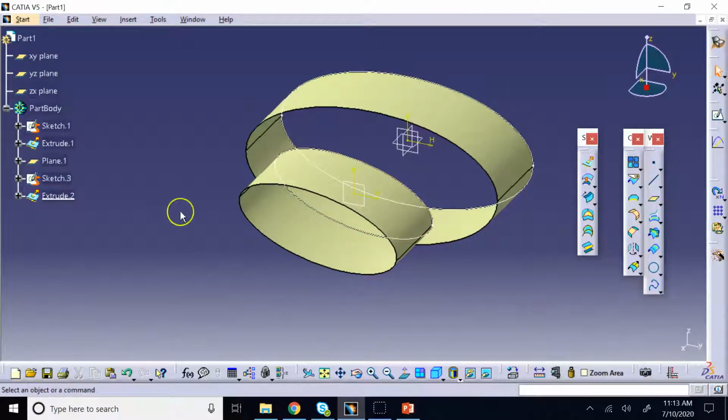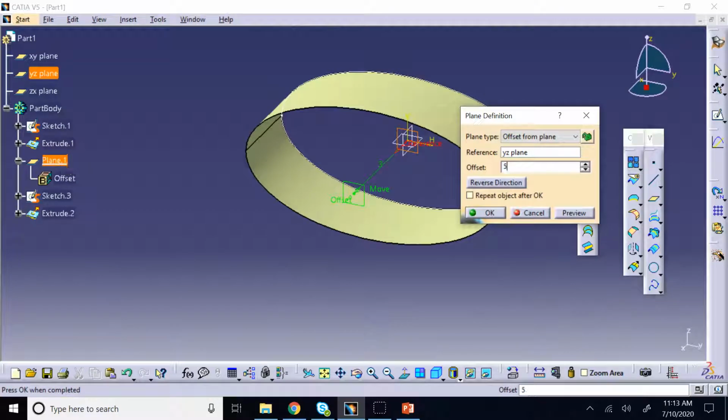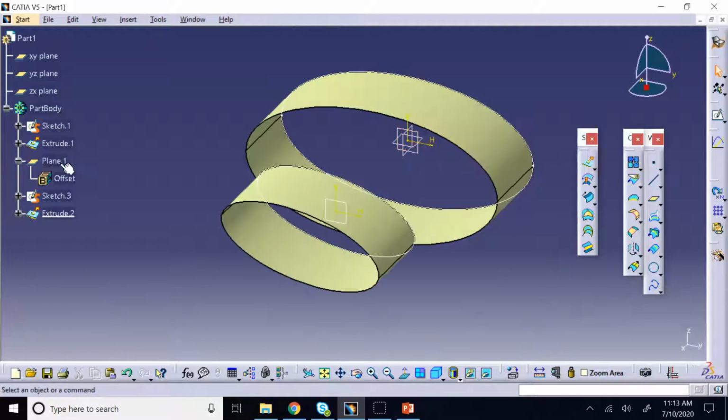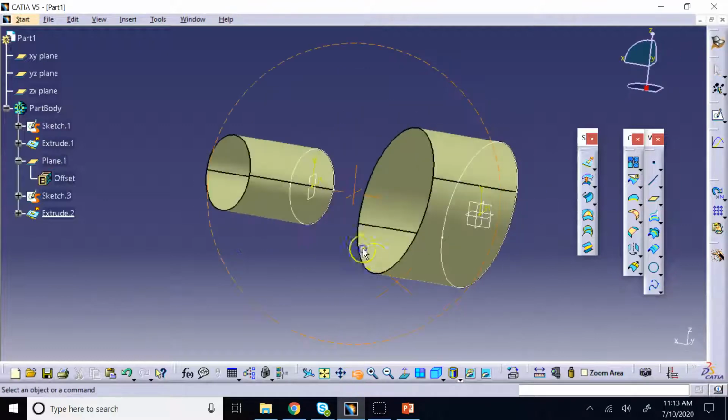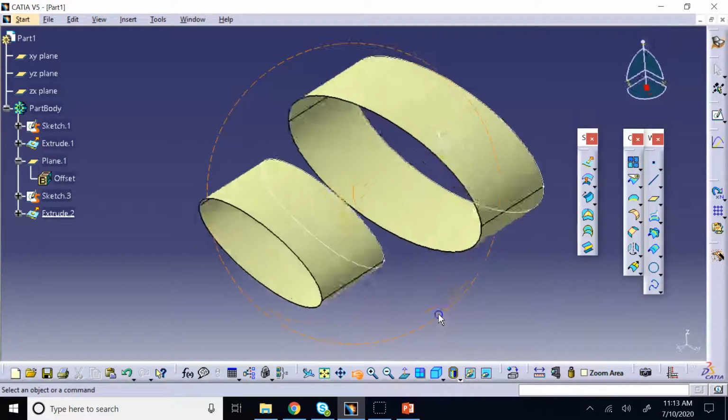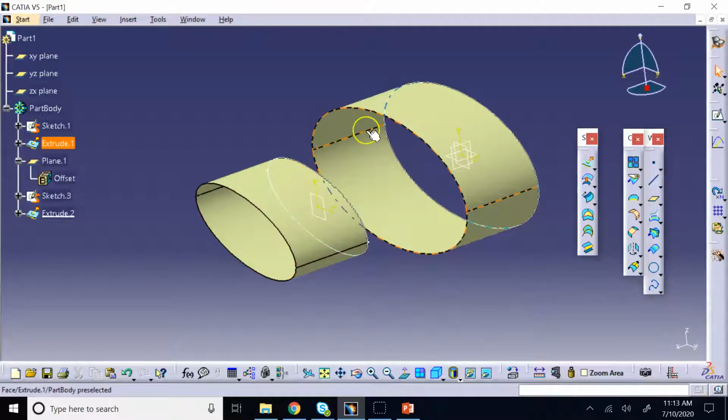Okay, so I have two disjoint surfaces, and these guys are completely separate. Their end profiles are not even on the same plane. Now, can I connect them together in a smooth way? You might say use multi-section. Sure, I can, but the multi-section is not going to be so smooth. In other words, this surface and the multi-section are not going to be super tangent to each other. I'm going to have sharp edges here and here. Is there any way that I can connect them together in a better way?